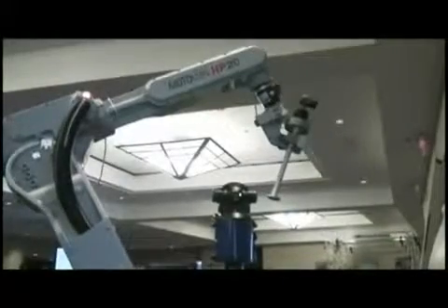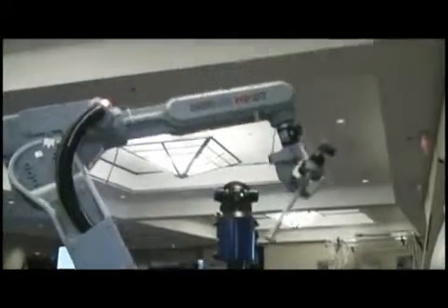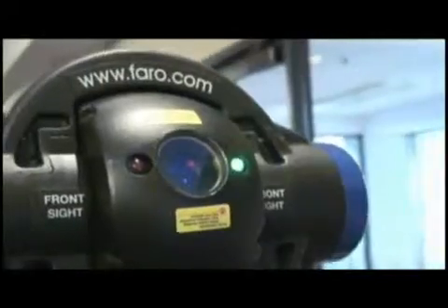Once the calibration is done, our software will compute the accuracy of the robot after calibration. And in many cases, we can get the robot to be well under 1 millimeter accuracy. In fact, in quite a few cases, we're within a half a millimeter or even a quarter millimeter accuracy. So by using offline programming and the FARO tracker and the Dynalog software, this provides a total solution for end customers to do high precision robotic applications, to do very fast and accurate programming of the robot.